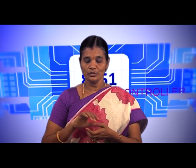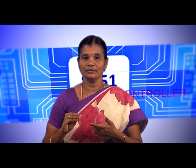Today we will discuss how to write the program to glow a particular LED at particular bit positions, or a group of LEDs, or all LEDs on or all LEDs off. For whichever port you want, you can use it. You simply initialize your required data: the bit positions to be on you put as 1, the remaining as 0. Then you read it in hexadecimal and move it into the accumulator. The accumulator is then moved to your required port.